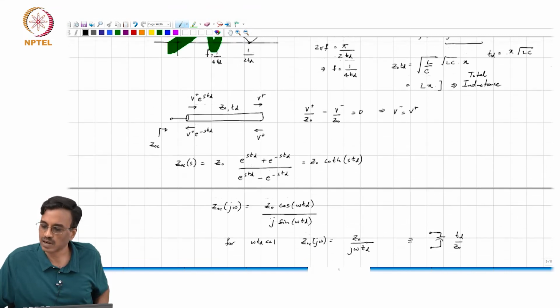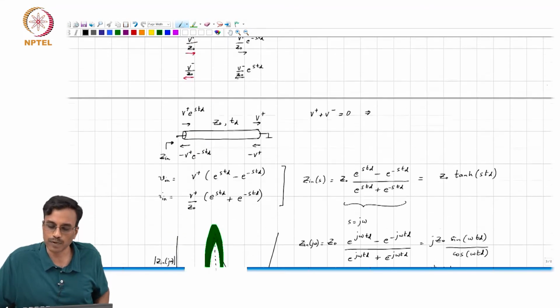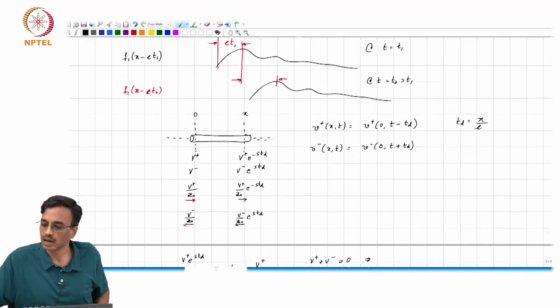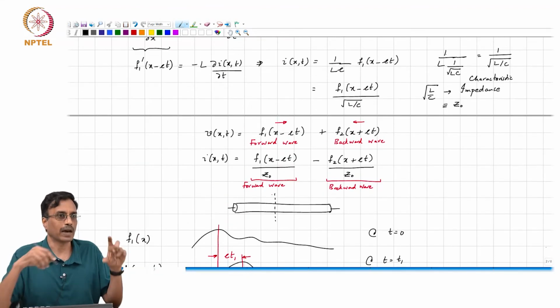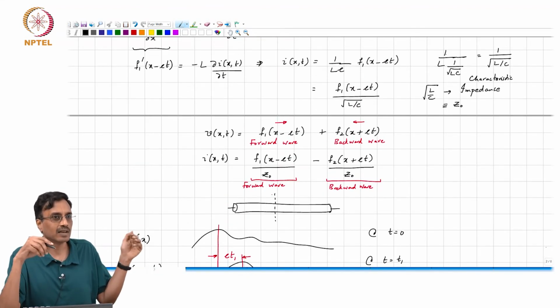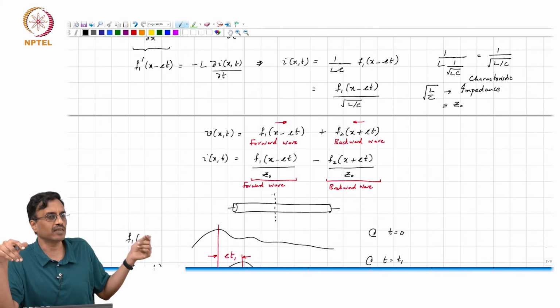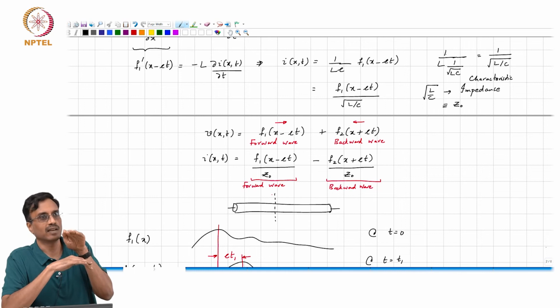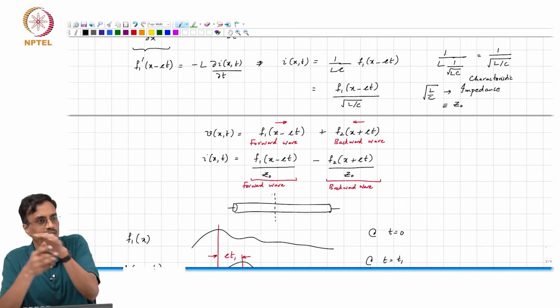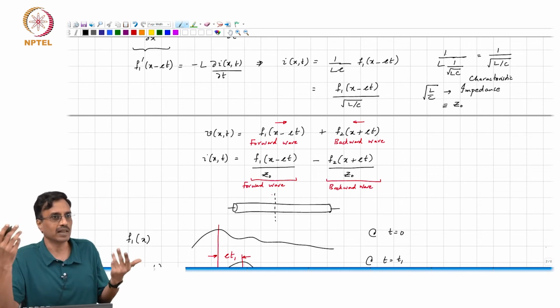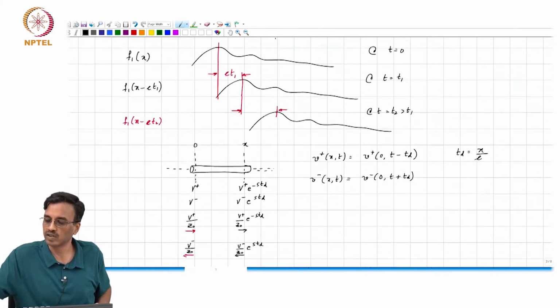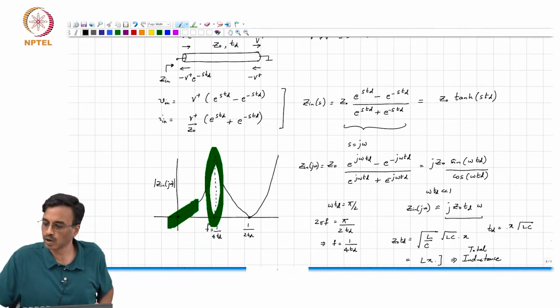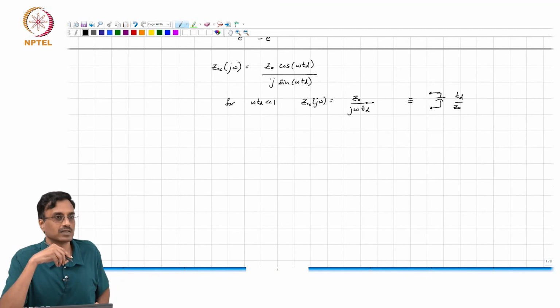capacitance in the transmission line, and that makes intuitive sense because at low frequency the voltage drop across the inductors is very small, it is an open circuit. So, the applied voltage appears across all the capacitors. So, the current that flows in is simply 1 over j omega C, where C corresponds to the total capacitance of the line, right.